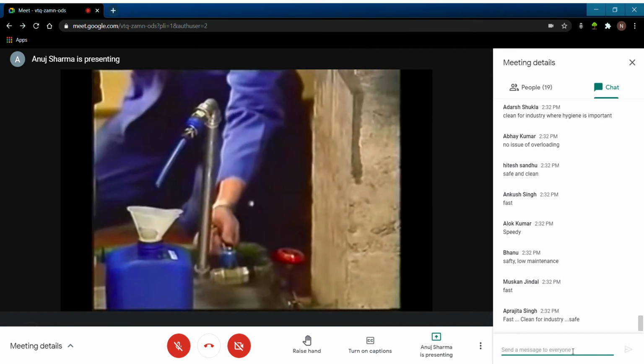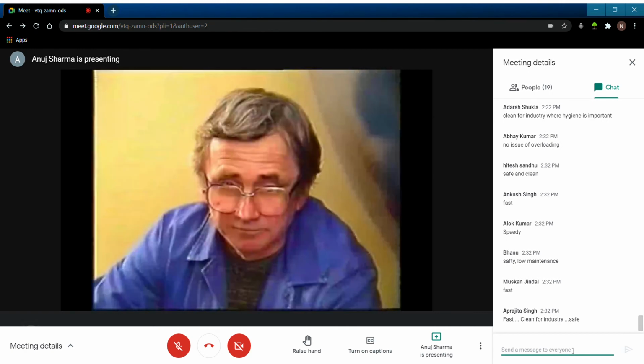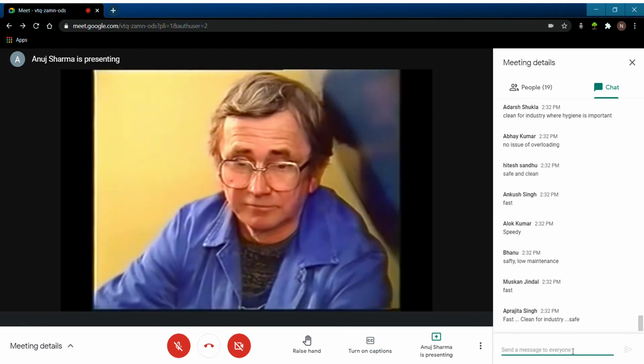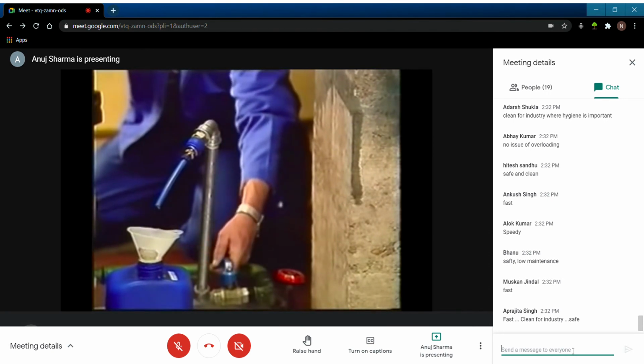In addition, the reservoir helps to cool the compressed air. As the air cools, moisture separates from the air and collects in the bottom of the reservoir. This water must be drained from the reservoir on a regular basis.